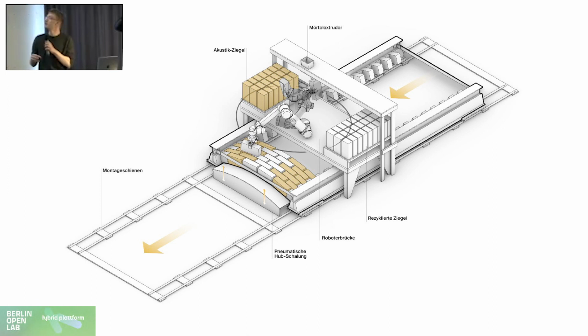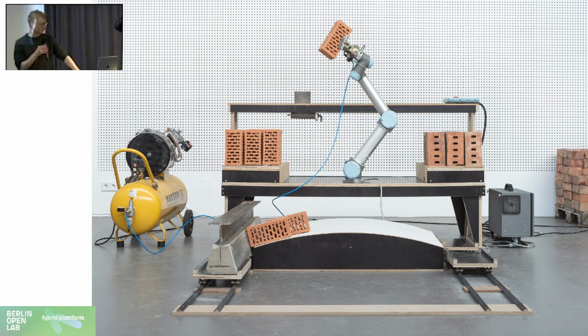Basic idea being you have a robot that can just place the bricks into this shape and do this in an industrialized fashion. So the whole system is running on rails and is actually quite fast in building these cap ceiling structures as a prefab element. So the prototype that you can also see in the MMD lab that is standing there, the pure building time of it is 24 minutes. So we did it in 2 runs. Each run was 12 minutes. Quite competitive for a first try, for building these things in a robotic way.